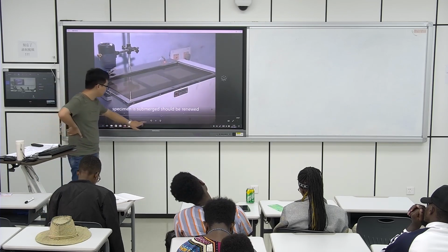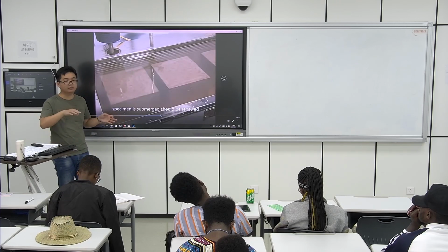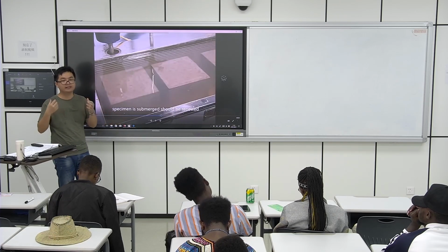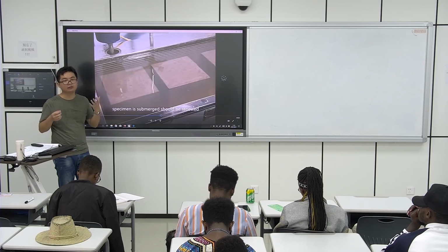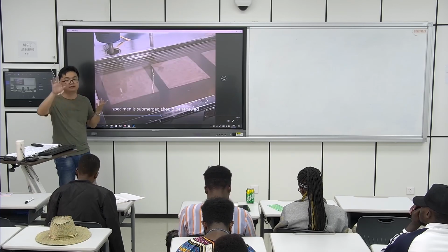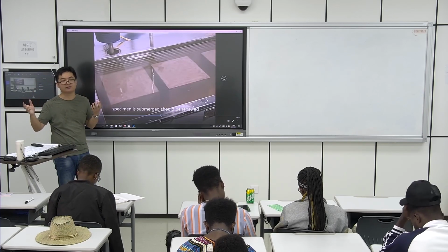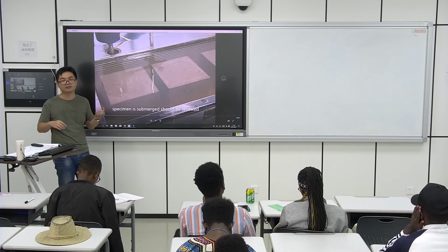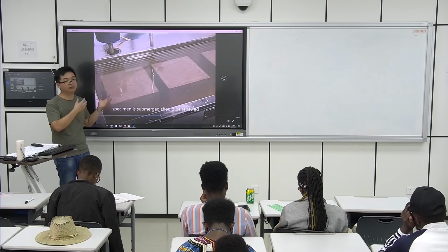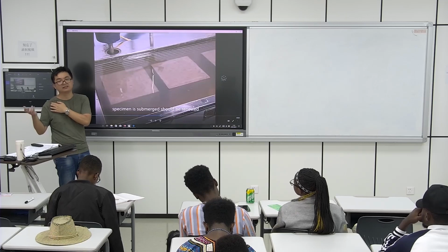Here, I explained the 7 days too, okay. Because people have established a formula, we can know the 7 days stress and then derive the 28 days stress. So it's okay, but if you get the 7 days value, we need to substitute the value into the formula and then get the 28 days stress.